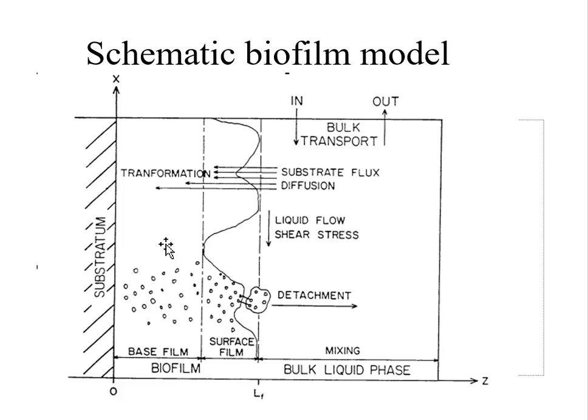And that's why in more modern biofilm reactors, like the one we have at the pilot plant down at the wastewater treatment plant, we have these small plastic carriers, and they move around a lot in the liquid. They collide, so biofilms, just by collision, have their growth limited. But we also have strong aeration, and these air bubbles cause a strong shear force on the biofilm, keeping it thin and efficient.